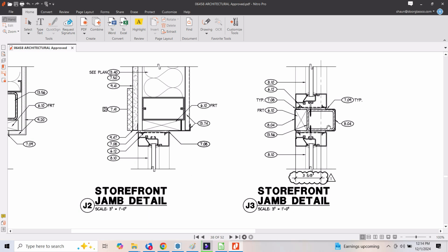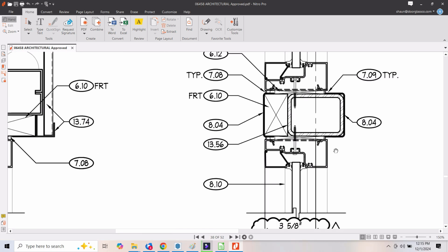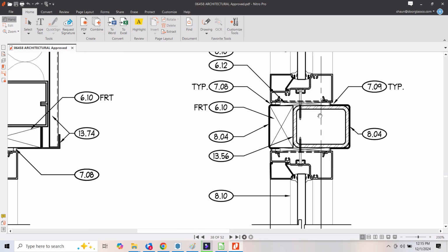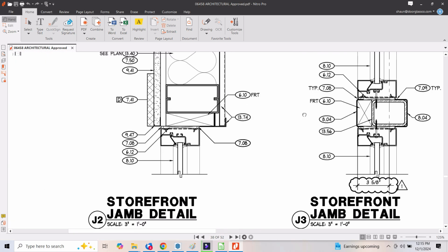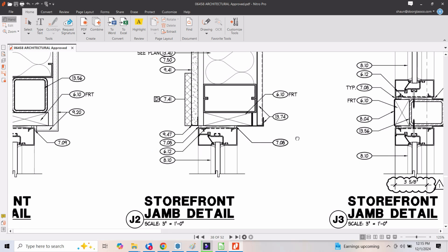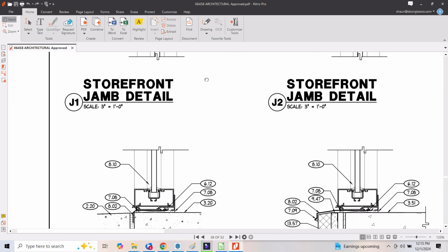And of course, the way that this is drawn up, the brake metal design is suboptimal. Sealing the frame to the brake metal cover, and you have all this extra sealant that is definitely not ideal. So we could probably build this in a much better way.